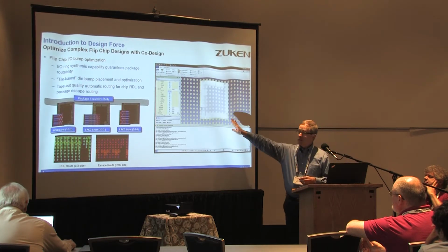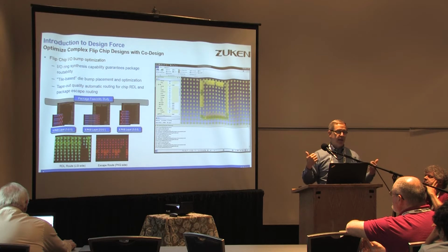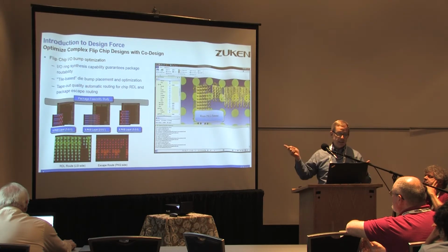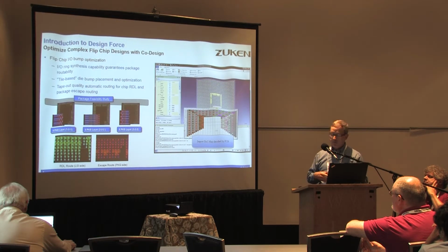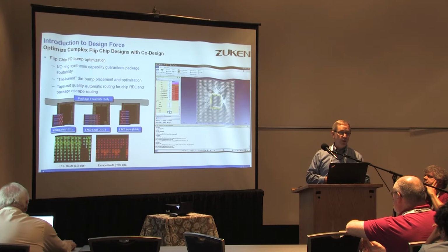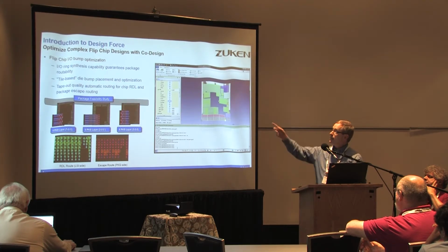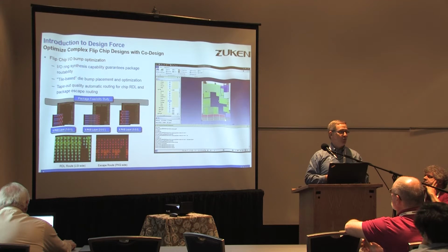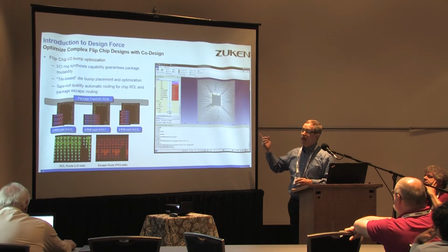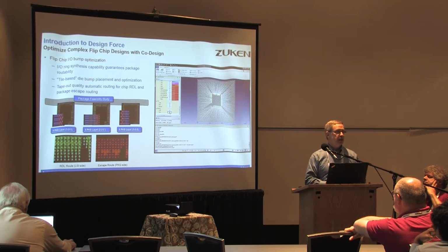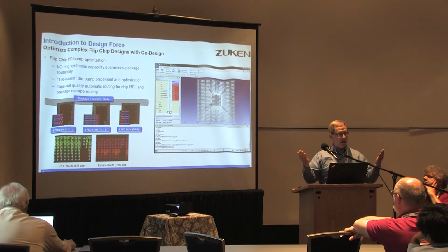We then take those results from the open access database and drive the pin out to the package. In this case, we're going to bring in a fixed pin out from a board team, in a ball map format. We'll bring in the ball map, and then we'll see that the rat's nests are not where we want them to be. So we will optimize the placement of the I/Os and the net assignment to the bumps, and correlate what's going on in this fixed ball out and this fixed die core, and map those accordingly with the I/O pad ring and the bump arrays.